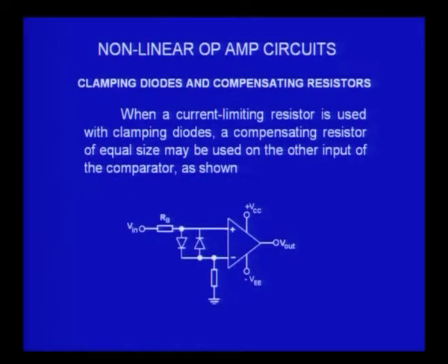This input offset voltage, generated due to the input offset current passing through the resistors connected to the 2 input terminals, can sometimes exceed 150 microvolts on the plus side or the minus side. When that happens, the output will switch state, even though it should not, according to the input voltage that I have applied at the input terminals. I hope you realize the situation.